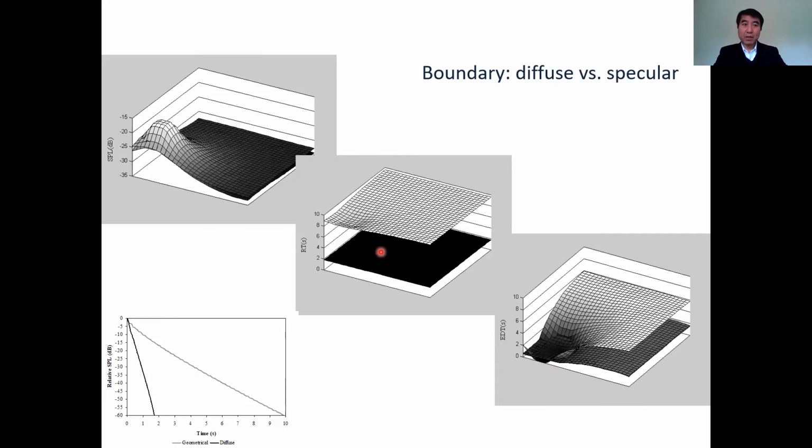And in previous slides, I always showed two lines. Maybe you noticed, one is a diffuse boundary, another is a geometrically reflecting or specular reflecting boundary. Architecturally, one is a smooth facade, like a glass curtain wall. Another is a diffuse facade, like a classical European facade full of decorations. So if you don't change the square's physical property and absorption, and just change the facade treatment from diffuse to specular or specular to diffuse, there are also some differences. That's the difference between the two extremes.